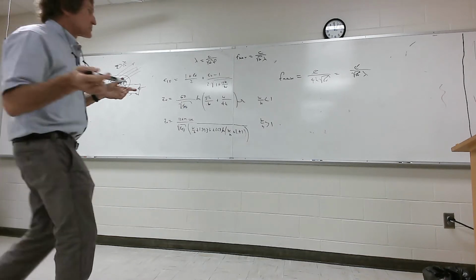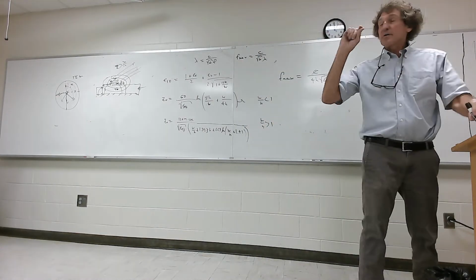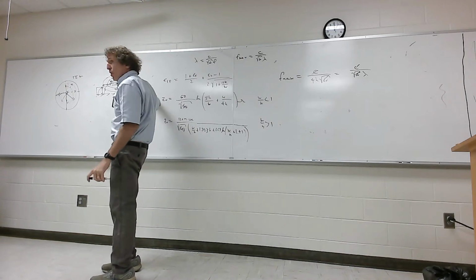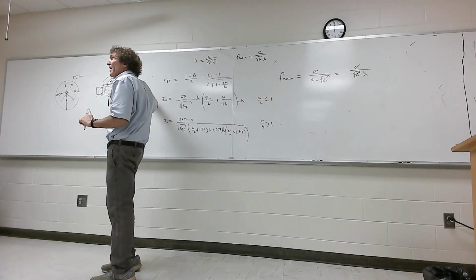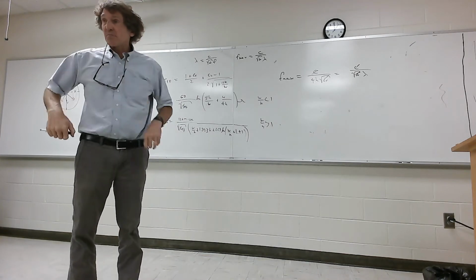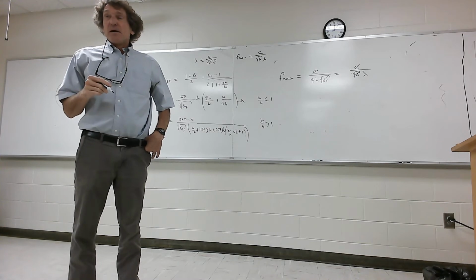I mean, you can use this formula that he has in the book, but I always think about it this way: anytime the frequency goes to a point where this is longer than a quarter wavelength in free space, then I know I got a problem. I've got multi-modes, I got other problems.